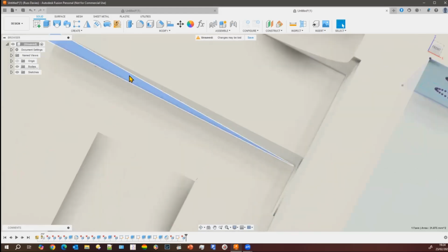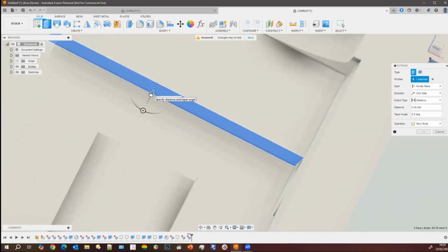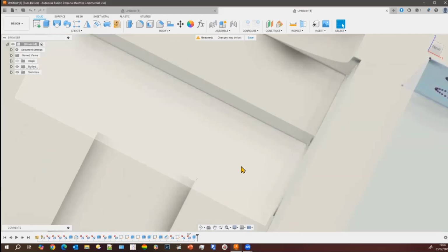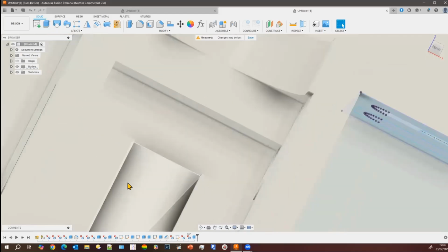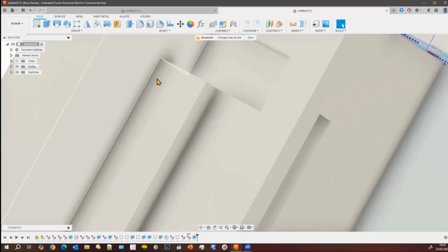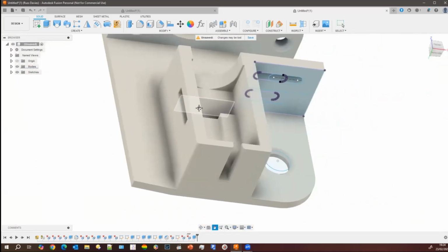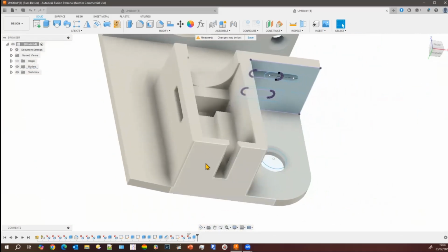So it's delete, and then you've got one face, and then you can make the slot wider to suit your particular stepper motor or servo if it doesn't fit this particular mount. And the same on the end there where the wires come out. Your wires might come out in a different place, so you might want to move this over to one edge or even to the side.